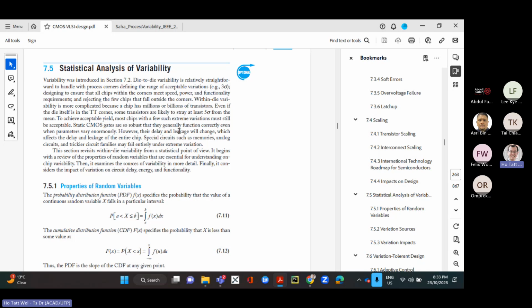It's not about the per chip, right? But if you're making like 10,000 chips or 1 million chips, maybe 3 of them will be much better than specs, right? But on average, there will be a few of them performing at this worst case. But you are selling all of them to the customer. You don't have the capability to test all of them. I mean, you can do a brief test, but you cannot test the speed and the performance of all of them. So what you do is have a specification that says all these chips, I guarantee, are going to perform above a certain frequency or at a certain speed. But how you evaluate the speed is not the design speed, because process variation makes that worse. And we're going to see how and why.